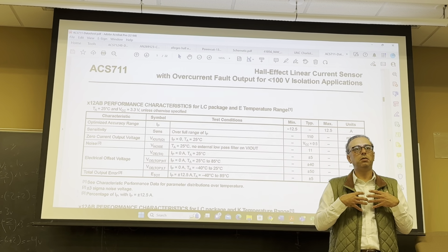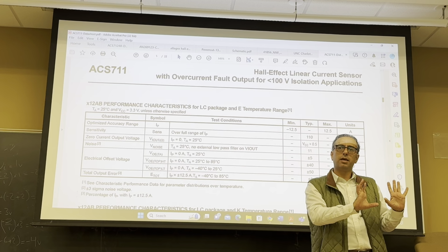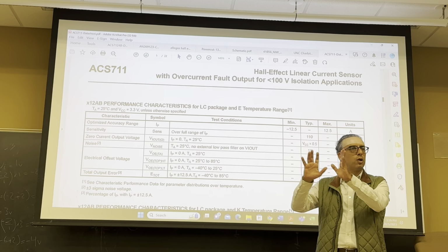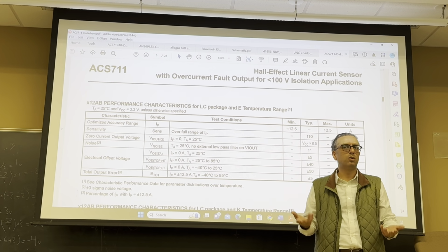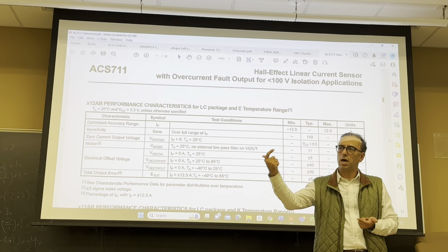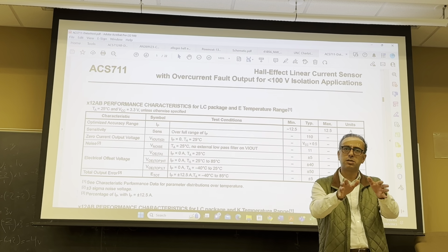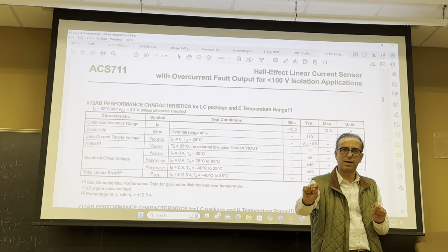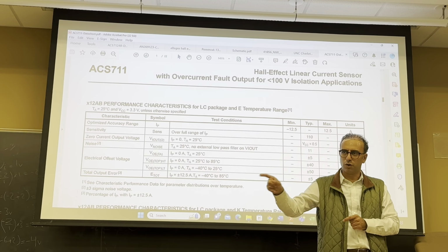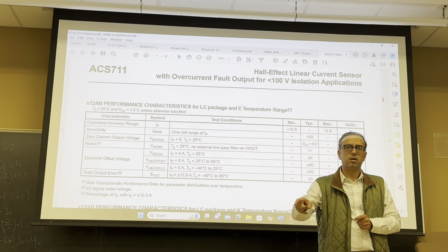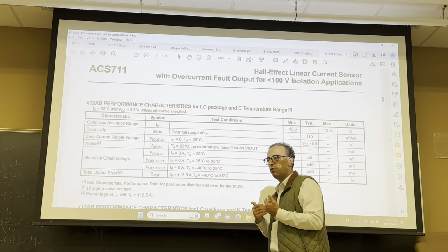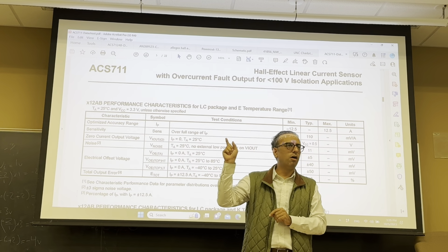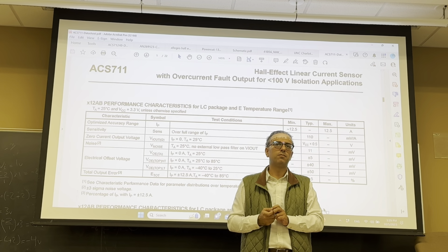But what I want to see is you have the schematic, you have the PCB layout. This layout has been uploaded to one of the manufacturers, including forpcb.com, and you receive feedback from them that this board can be manufactured, and there is no manufacturing error. They don't check that it's working for your purpose, of course. So essentially, your deliverable would be the screenshot of the approval from the manufacturer, right?